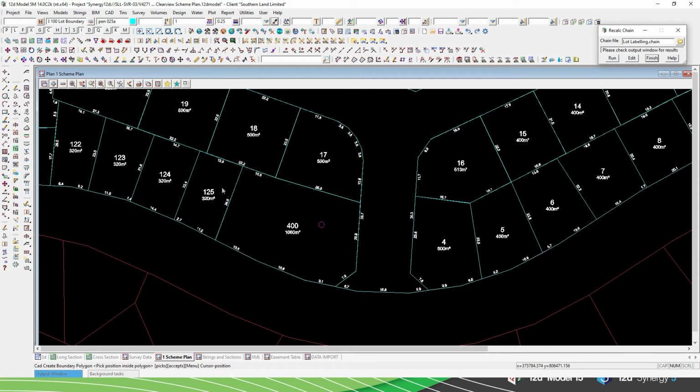What I'll do in this demo is I'll take our stormwater reserve. Let's say we're able to use dynamic analysis to reduce the size of that stormwater. This is actually something that did happen in this project. Once we got the dynamic analysis up and running and finalized our storage volume, we were able to fit a few more lots in. So later down the track, we could add a few more lots and subdivide a few extras off.